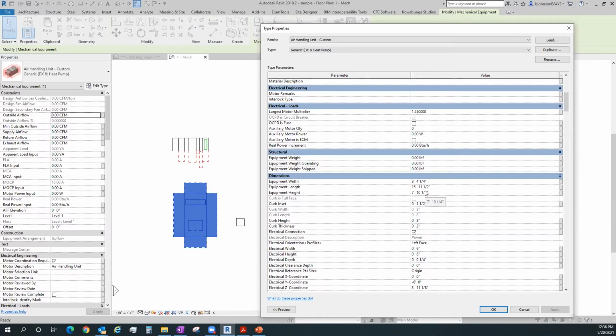actual dimensions. So no matter what object you would get back from, say, Trane or other mechanical companies that do air handling units, you should be able to come in here and say, I want to change my length, width, and height to the actual cut sheet length. And you have a realistically real object by size at that point, as if it was just my placeholder cube with these 3 dimensions, right? But it also has the red areas or the dashed areas that come off the side of the box. There's clearance areas, which also have their component to do clash detection with, right?